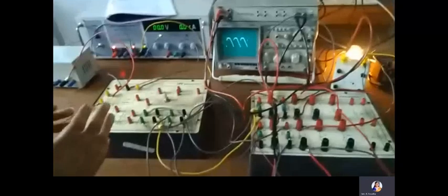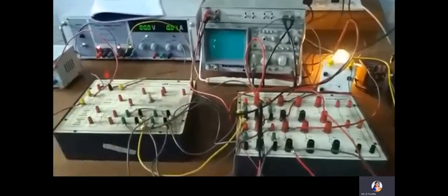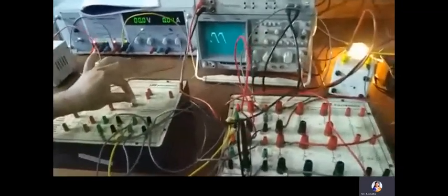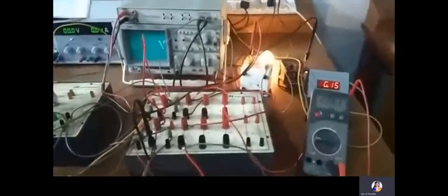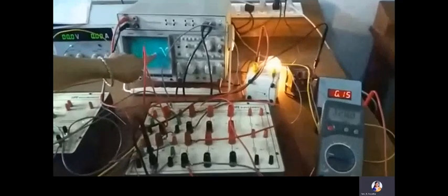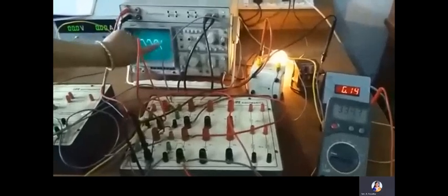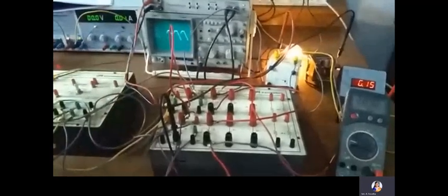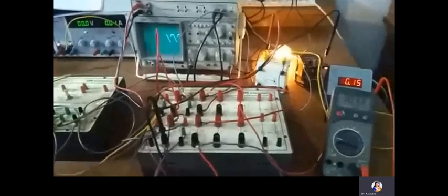Now the waveforms and voltage across inductive load, that is RL load, in case of fully controlled rectifier. I am varying alpha. When alpha equal to 36 degrees, the output voltage is 311. You can observe here during the period alpha to pi the inductor is charging, and during the period pi to beta the inductor is discharging. This is the reason why the supply voltage negative cycle is appearing across the output. We didn't use a freewheeling diode here. This is the reason why the supply voltage is appearing across the load.